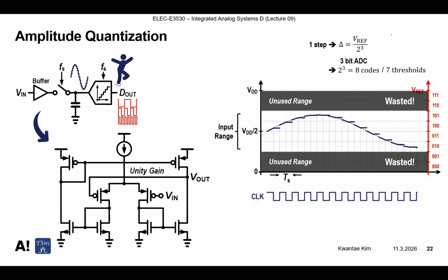So this happens, for example, as I said, if you recall CAD exercises 2 and 3. We put the amplifier in a unity gain configuration, and this is limited by the transistors, PMOS VDS, NMOS VDS.